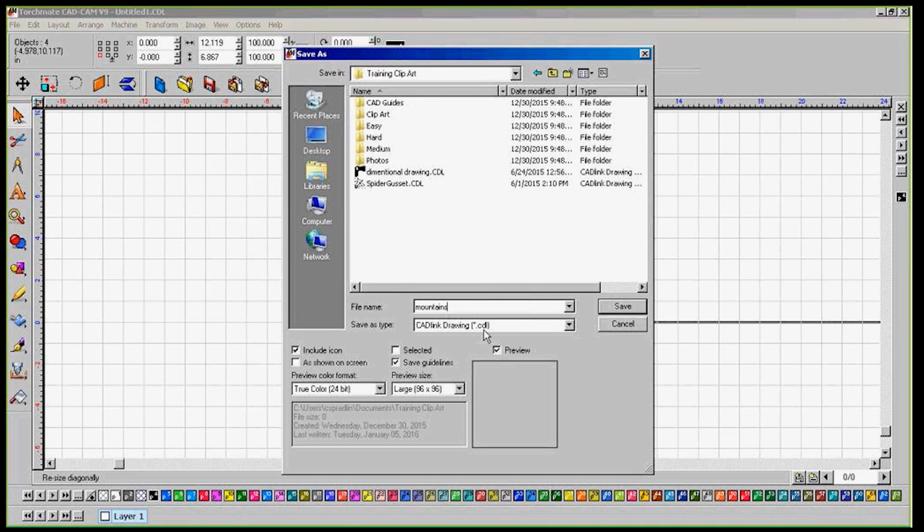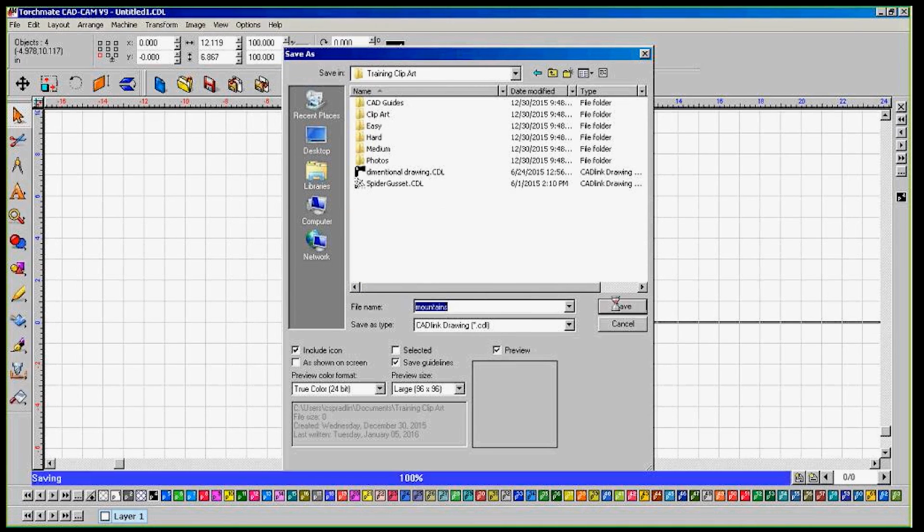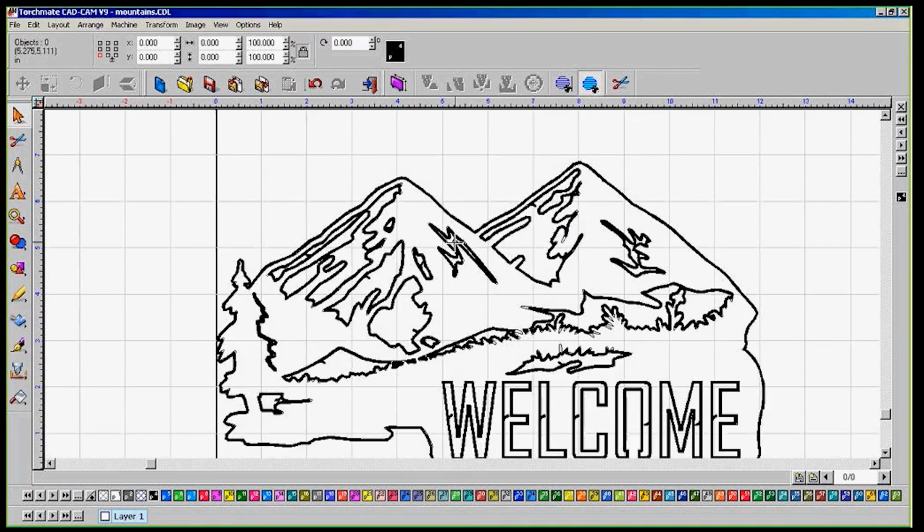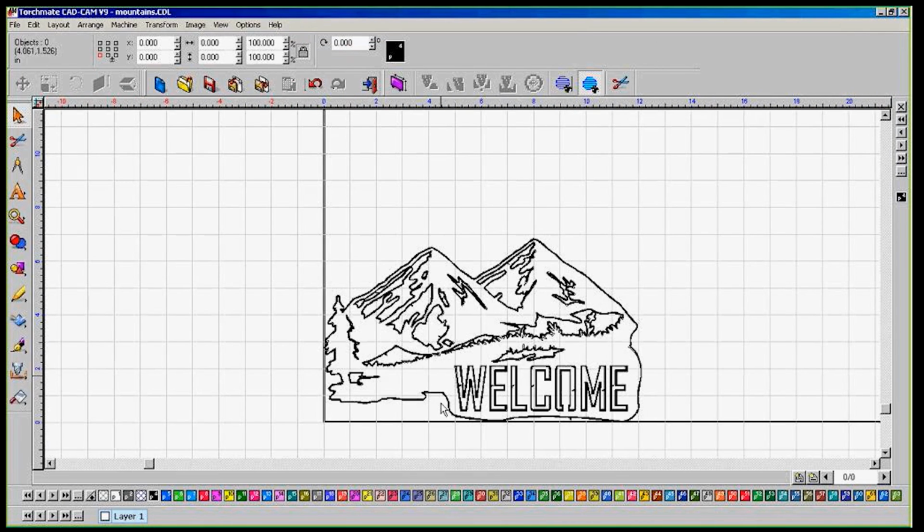I can't remember where I got them from right off the top of my head, but it doesn't mean that you should always do the shape, but just make sure that if you do have straight lines, that they're separated out from everything else. So you would just select all the straight lines and then arrange make path on those, and then arrange make path on all the other ones. And then you could do an online for the straights and then a male-female for the other shapes.